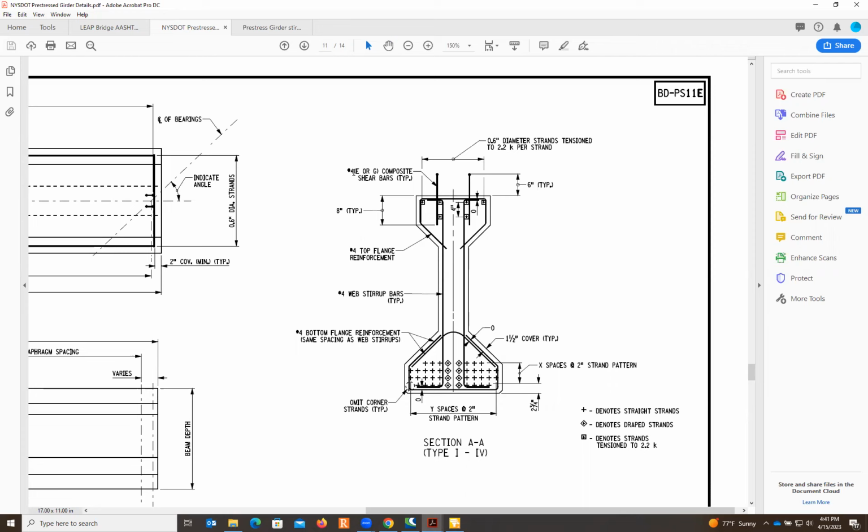And we do have these number 4 shear bars extending into the deck to make the girder composite with the concrete deck. So those serve like shear connectors extending into the deck, which is number 4, epoxy coated. So this E represents epoxy coated or G represents galvanized.